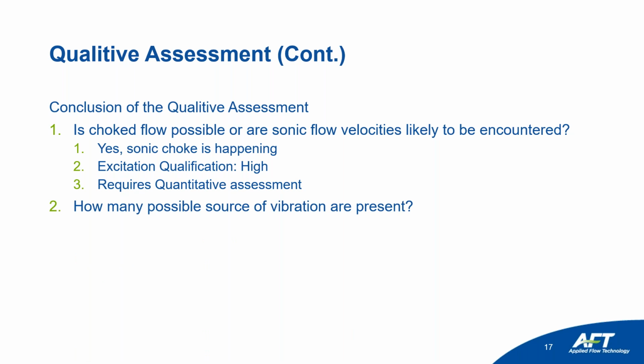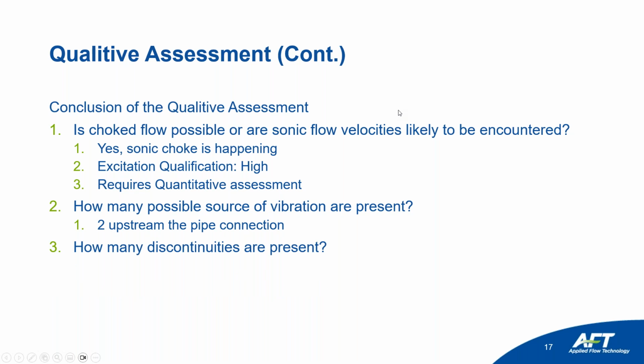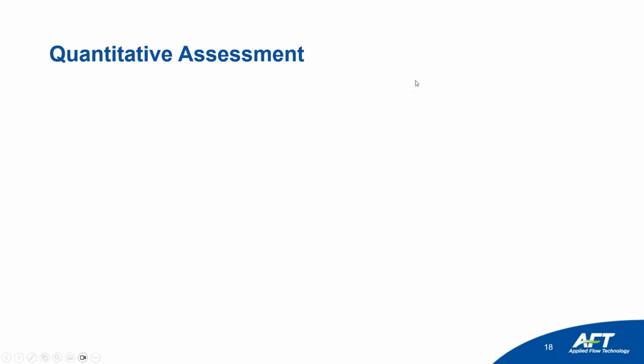How many possible sources of vibration are present? Well, upstream of the discontinuity, we have two possible, two upstream pipe connections. How many discontinuities are present? We only have one. So now we go to apply the quantitative assessment, the second stage of the Energy Institute methodology.